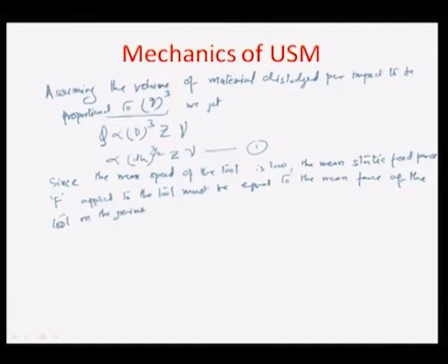Now, the duration of such an impact is assumed to be some small value delta t, let us say, and the maximum value of the impact force can be something like Fi max. Okay. The nature of variation of F with time can be plotted and seen, and the behavior can be estimated as how the force would vary from the stage that the grain is coming in contact with the tool, to the stage that the grain is getting plowed because of continuous hammering of the tool, to the stage when the material gets dislodged and the grain becomes a free grain to move along with the slurry.